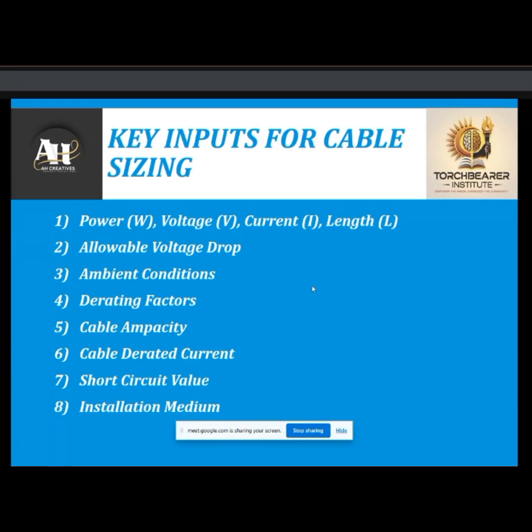For the DC strings, we have to combine our number of strings, and then multiply the number of panels in one string with the operating voltage of the solar panels. And the other one is the current. For the DC level we use the string current, and for the AC we use the current output of the inverter.